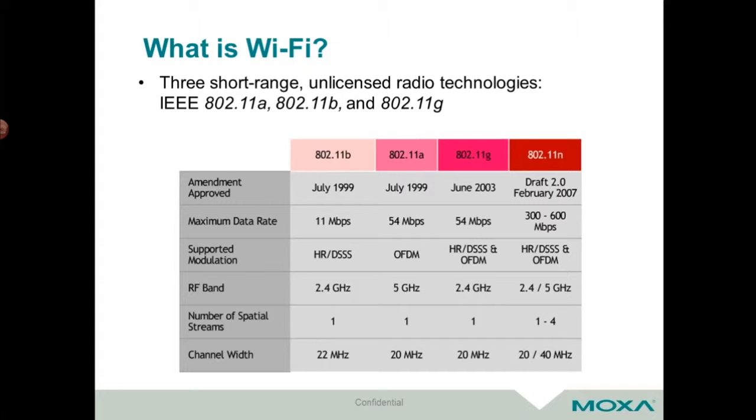There's an inverse relationship in wireless between frequency and distance. The lower the frequency, the longer the distance the wireless communication will travel. That's why when you see things like 900 megahertz systems, those can travel upwards of 10, 20, 30, 40, even 50 kilometers away. It's because they have that lower frequency associated with them.